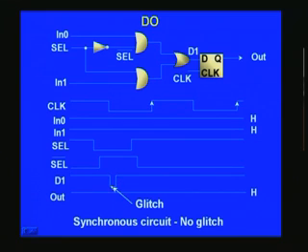Now if you process this elsewhere without the flip flop, what will happen? It may so happen that when your circuit is sampling, it may sample at this point, and that is not the desired point. You wish to sample only when the actual D1 is high, but you might sample here without your knowledge. So that will play havoc. Had you given this as a clock input for some other circuit, I don't have to tell what the implication will be, and therefore it is very essential that we get rid of this glitch at all costs,